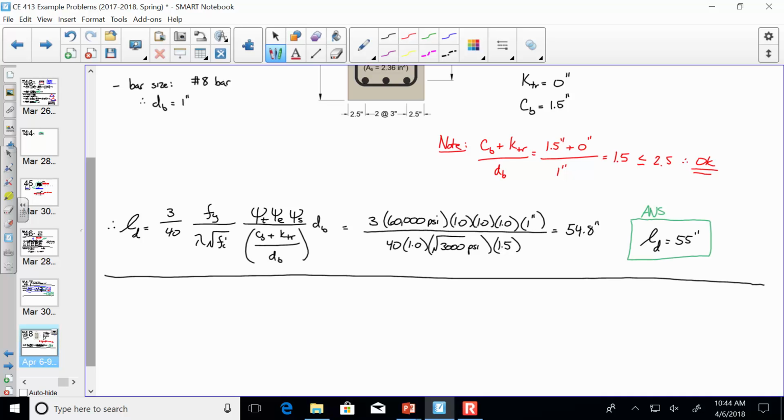One of the ways that you could substantially decrease the development length of a bar is to bend it. To actually bend the bar into a hook. Because you're embedding a hook, now the concrete has something to hold on to. Instead of, if I was holding a rope or holding somebody's hand like this, what if I'm hooking it in? Now I've got a much stronger bond, and that development length could go down. There's a whole bunch of strategies that you can use to take this number and chip away at it. But we're going to take them one at a time.